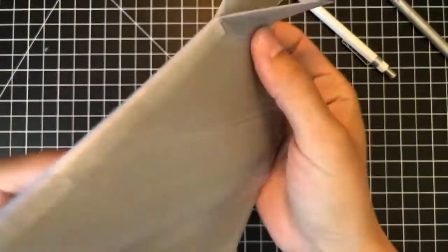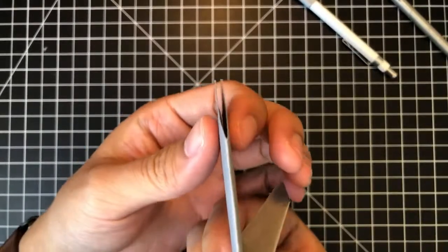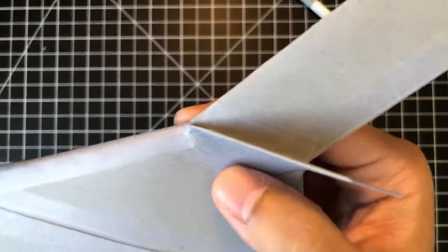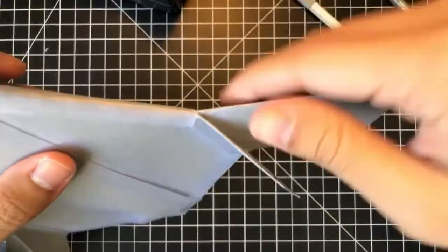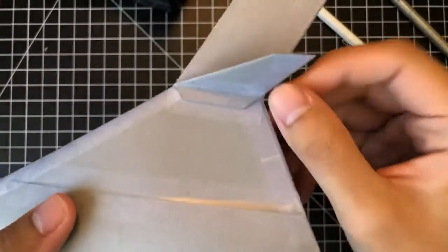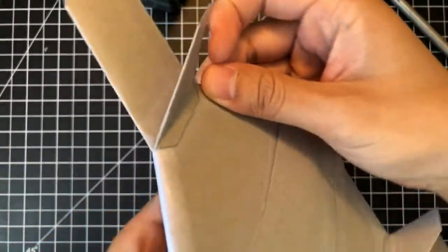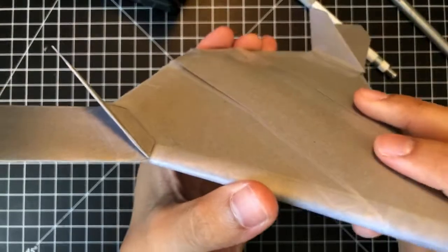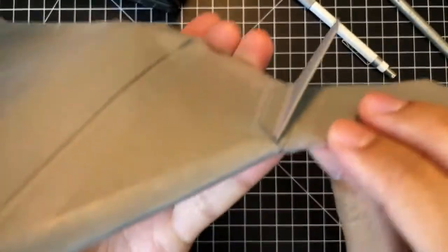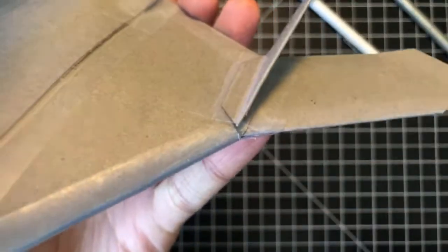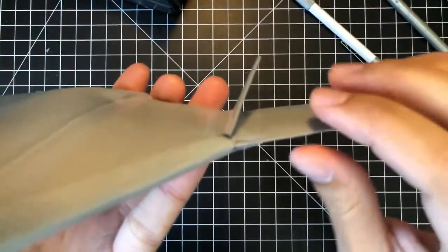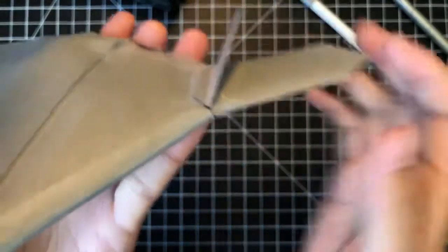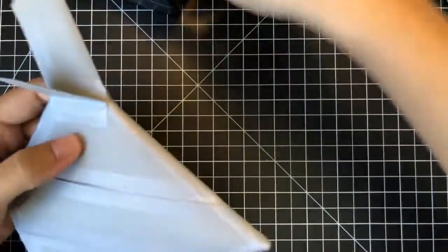And mainly right now, I'm looking at the places where I need to apply some tape to really close it off. I feel like the vertical stabilizer is one of those positions because this is a separate structure that's been taped to the wing body. And so on this side especially, it's really obvious that it's kind of lifting off. And so this would cause some level of drag, so we need to tape that down.